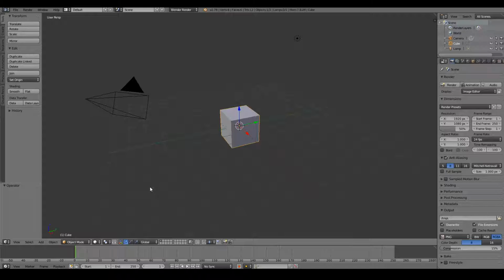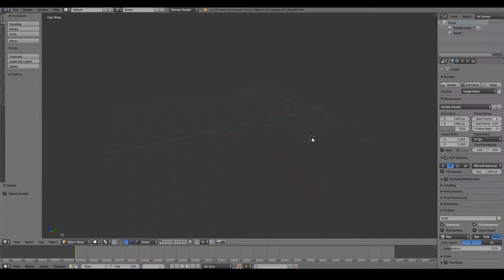Just a final thing before you end off, I'm now going to Blender, and I'm going to use Blender to plan out our scene. So let's just delete everything in our scene by pressing A maybe twice, and then X, delete. Now I want to go to the top view by pressing 7 on the numpad, and then pressing 5 to be on orthogonal view, which is a more accurate view.